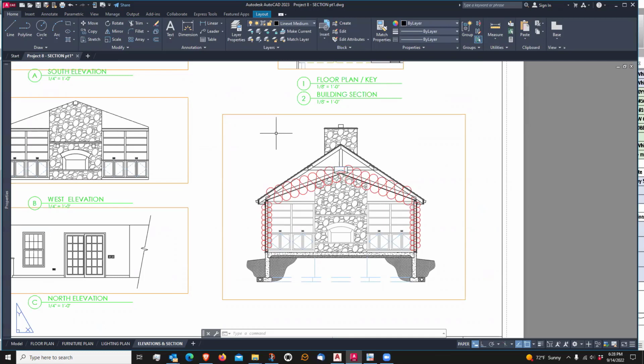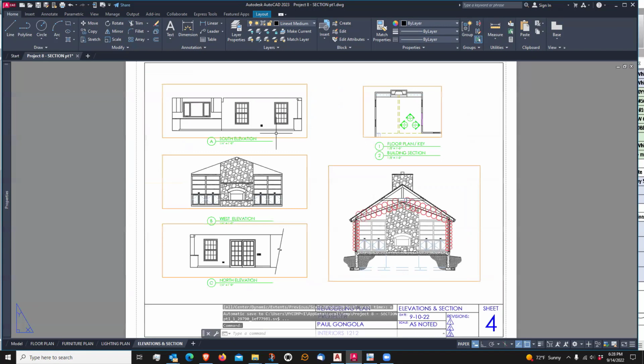And if I just zoom extents here, and type regen, R-E-G-E-N, it doesn't look like anything happened. What it did was regenerate my paper space here, but it didn't regenerate the viewports. So there are two ways that I can handle this. One is to double click within the viewport and regenerate it.